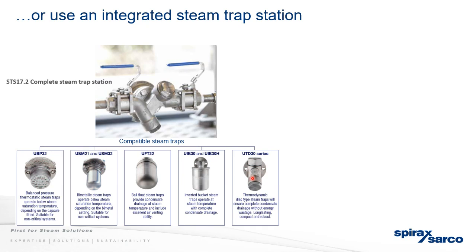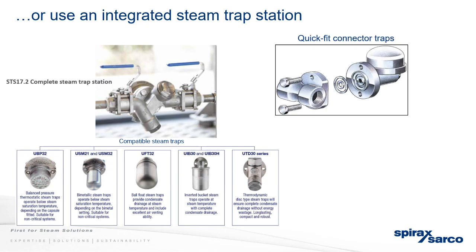Yeah, and they're available in flanged, screwed, and socket weld. Yes, they are. Is there any questions on these? No, we can carry on. Okay, so as we said there, they're a quick connector for the traps. So as we showed before, it's a very 5-minute job to change the trap.